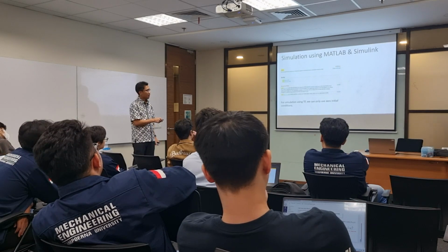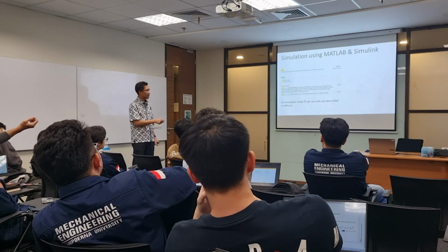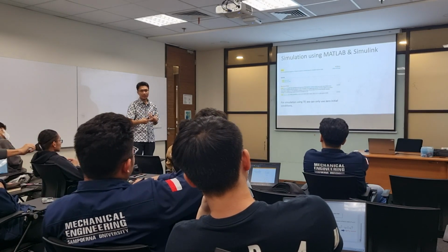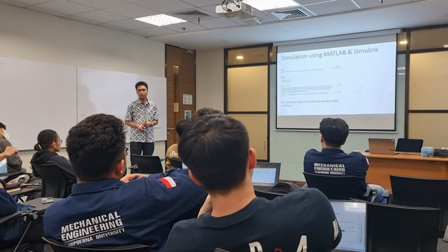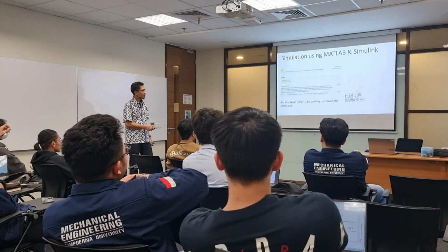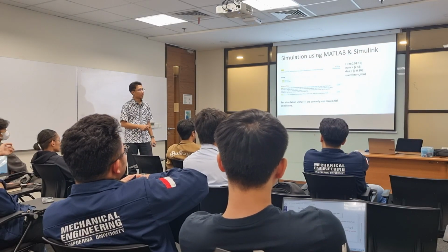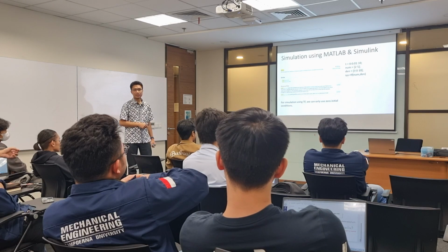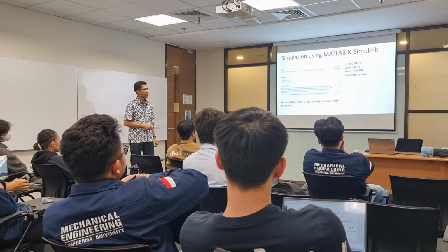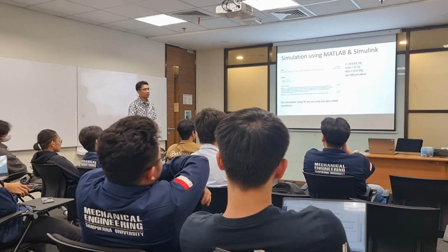So this is the syntax. Very easy. You put your sys first, then your control input, and then the time array that you want to simulate. The time array is free; you define it up to you. As an example, I first set the time frame from 0 to 10 in increments of 0.01. That's the increment. And then this is the transfer function from earlier, numerator and denominator.